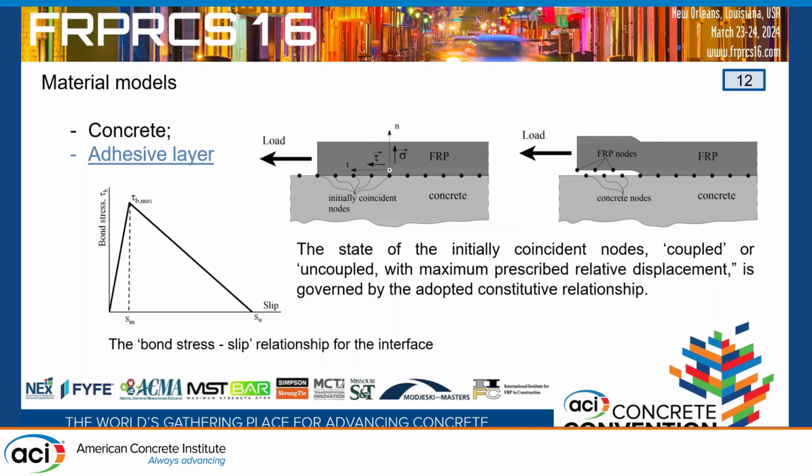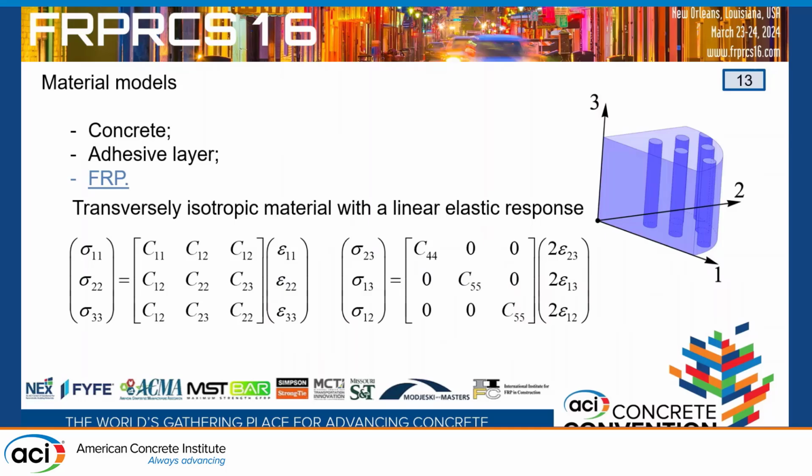As a function of the shear stresses you have at the interface, you have some prescribed displacement, for example, of the FRP nodes with respect to the concrete nodes. Finally, when all the nodes are separated, you don't have any more rigid body, and the analysis stops. The FRP material is linear elastic until failure in 3 dimensions; unidirectional FRP should be modeled by defining 5 model constants.